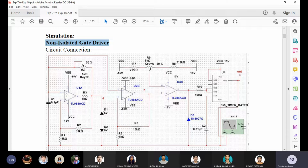My suggestion is to download the data sheet of the TL084 and see where the VCC is. The plus VCC, the positive biasing voltage terminal, is pin 4, and the negative VCC is pin 11. A ground terminal also is there. Total 4 op amps, 3 into 4 is 12.